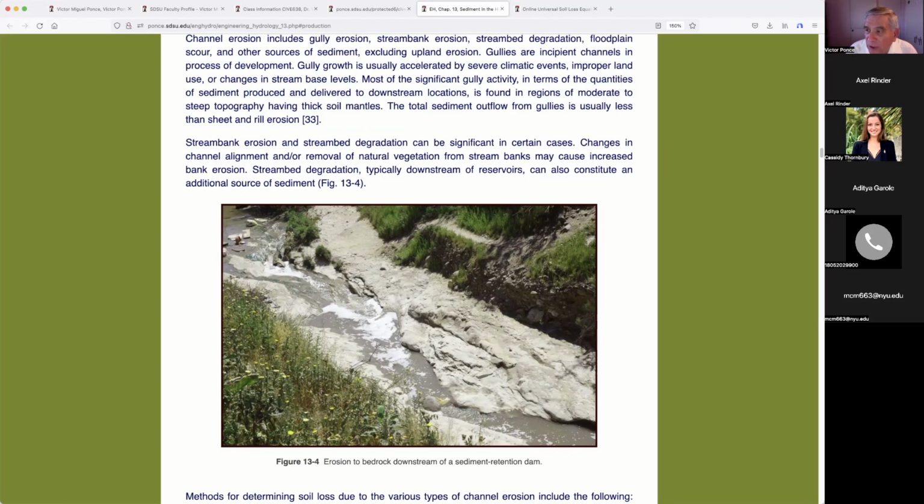Sediment is always moving. There is a certain truism in this. We have to let the sediment move. What we should not allow is large quantities of sediment to move in places where there was no such movement, because if that happens, then we'll have to contend with the deposition downstream. It would be like in a river. It could deposit in a river, and then the river doesn't carry any floods. Then we have to be called out there to figure out what to do with the river, because the sediment that is occupying the bottom of the river would be a problem, you see?